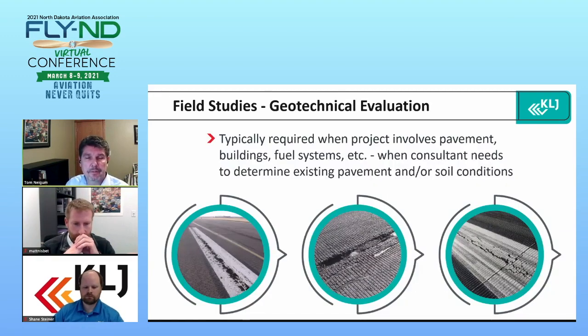At the same time, there's probably going to be a geotechnical evaluation that needs to be done. That's where the consultant's looking for information. If it's a paving project, if it's existing paving, they're going to pop some holes through the pavement and determine how thick the pavement is, how thick the base is, you know, what's underneath it as far as soils, in order to do the pavement evaluation. For buildings and fuel systems, there could be foundations that need to be installed. So there we may need to do a deeper investigation. It really depends on the project. And really it's to find out what's there so that the consultant can make an adequate design.